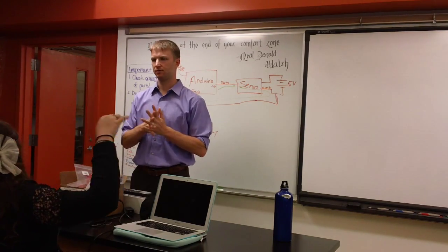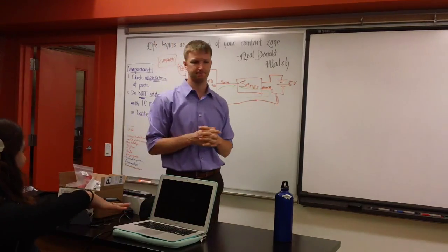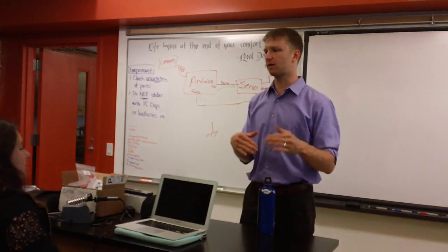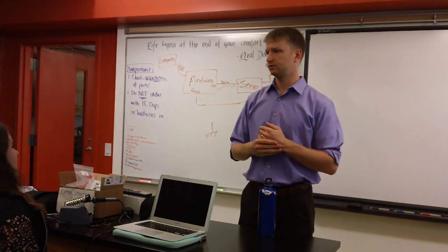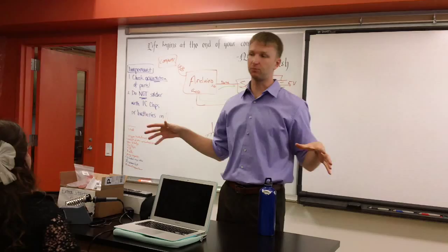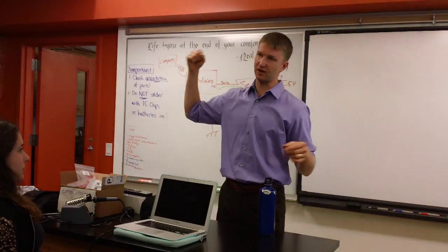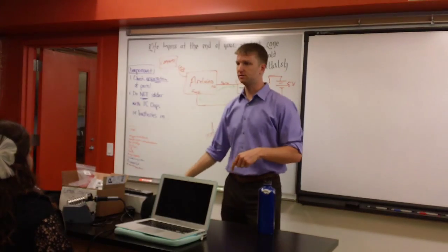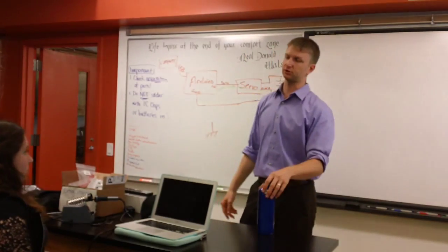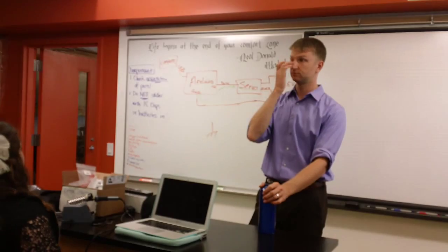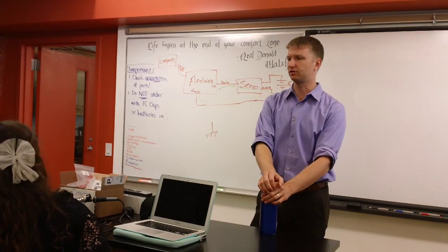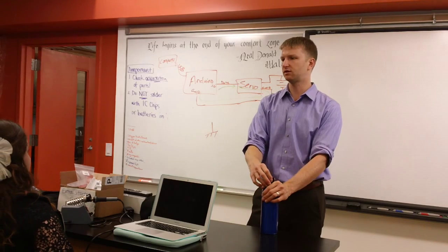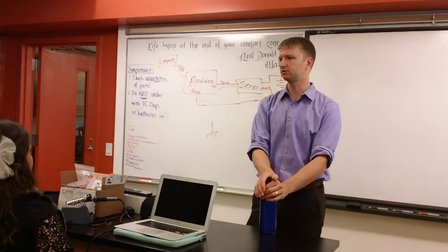Yeah? So like the entire ground is like electrically charged because of that? Well, it's not charged. Remember, it's just a reference. So it's all the same reference point. If you put a stake in the ground here and a stake in the ground on the Lower East Side, they would be at the same potential. Now it's not as good as connecting with copper, so you wouldn't be able to do real fancy communication stuff, but it's about the same voltage, so you could talk.